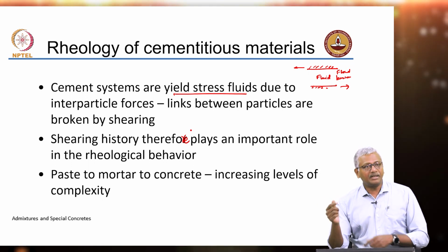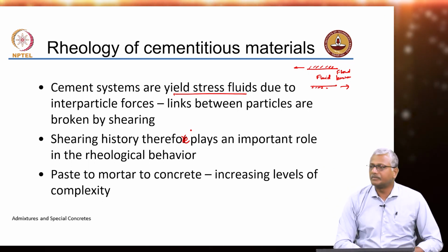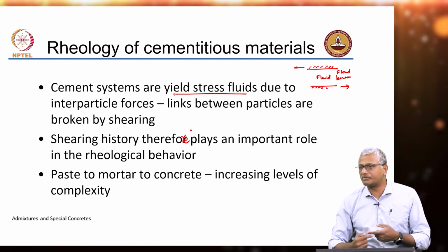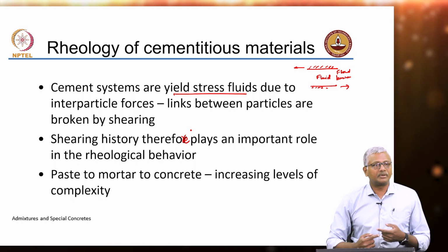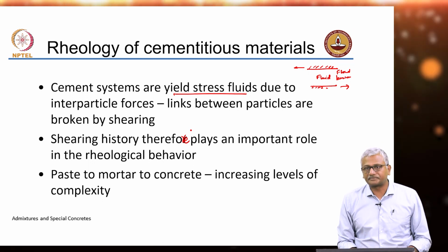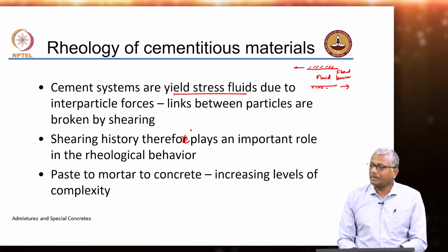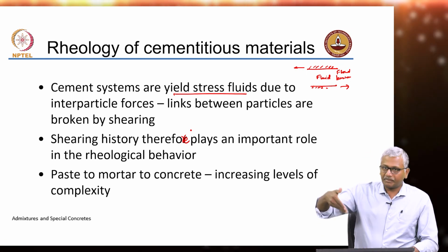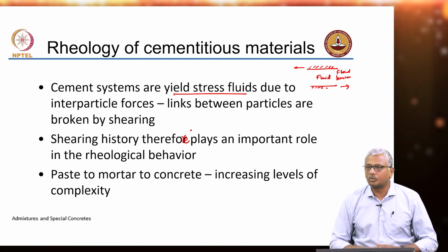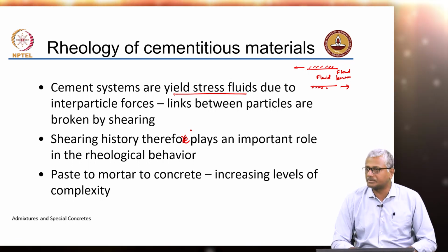Okay. Secondly, if the same truck continuously agitated the concrete while you are bringing it to the site, you have continuously broken up the internal buildup of the structure. So, if I apply this shear continuously, I am not allowing the structure inside to get built up. That is required when I deliver concrete, but that may not be required when I place the concrete. After I place the concrete and the concrete is stable, I don't want it to be able to flow continuously. So, it should have an internal buildup that allows it to stand inside the formwork without too much deformation.